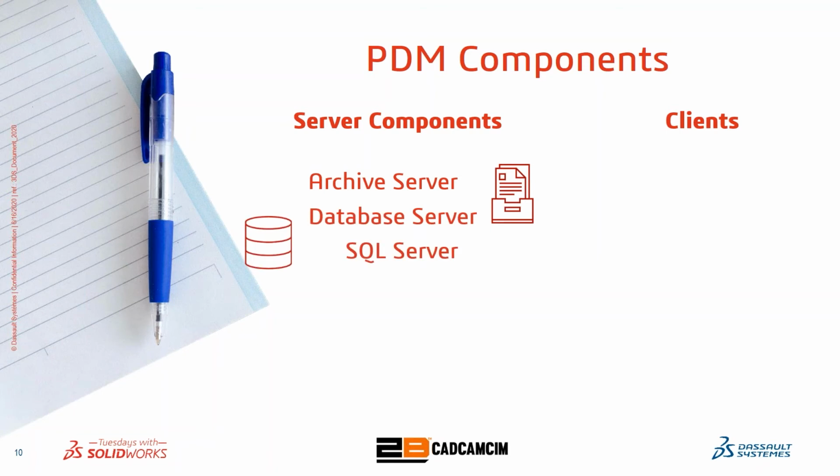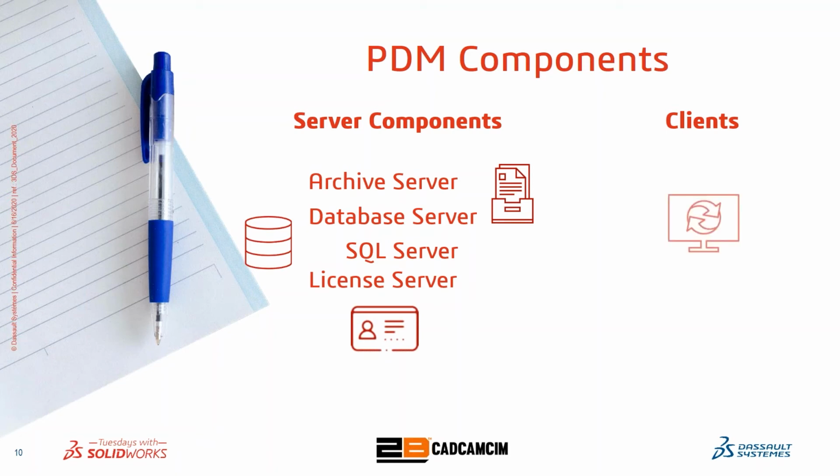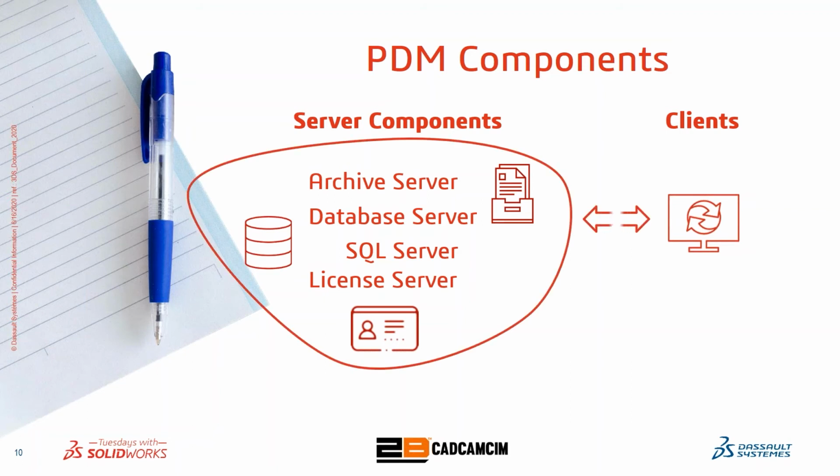Then the database server, which must be hosted in SQL Server, and this is responsible for managing data in the archive server. Number three, we have the license server, which is responsible for license distribution for clients who want to use SOLIDWORKS PDM. On the other side, for clients, we have only Vault View. Vault View is actually communicating with all three server components: the archive server, the database server, and the license server.